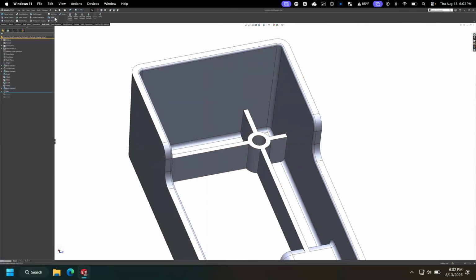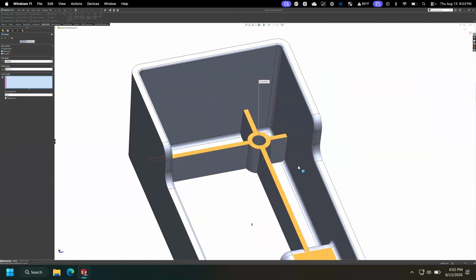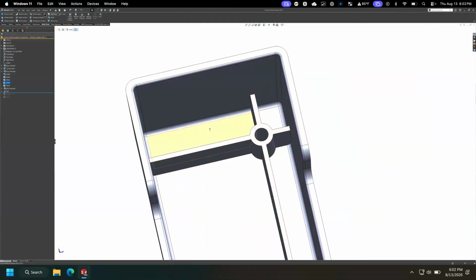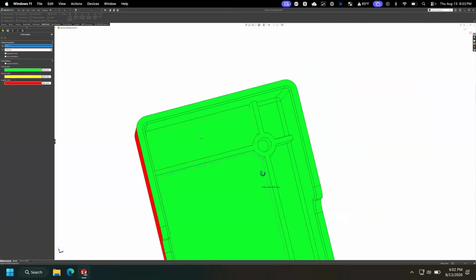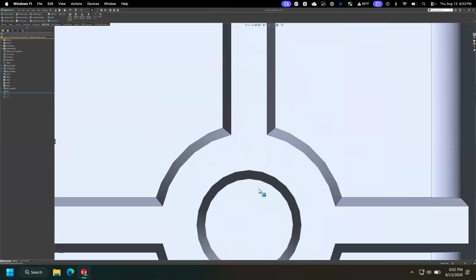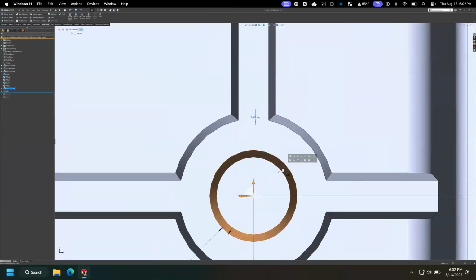Is that drafted opposite of the outward draft? No, he doesn't have any draft at all. I think currently the way this was designed, it doesn't have draft on it, right? I actually don't know. No, I think actually it does. Yeah, so he's got draft on that. So that's drafted inward on that hole. But you could put 0 draft on it. Yeah, this is currently giving me a thicker base, but our rib thickness was already at half our material thickness, so it's unlikely to give us much issue.